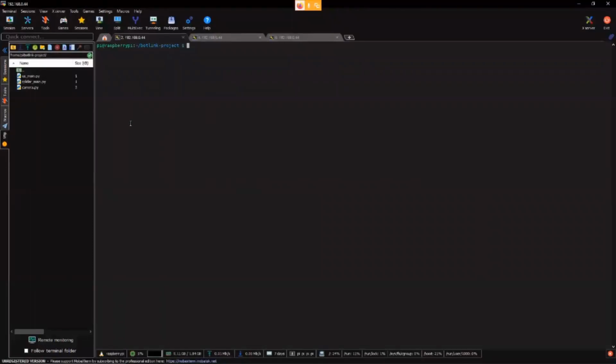The second script is the ultrasonic one, where it will read from the serial port and then trigger a GPIO power output onto it, so that it can read for 0.0001 second. And the last script is the camera one, where it'll read from the camera and send it to an HTTP server, where we can view that on any browser or through the app.